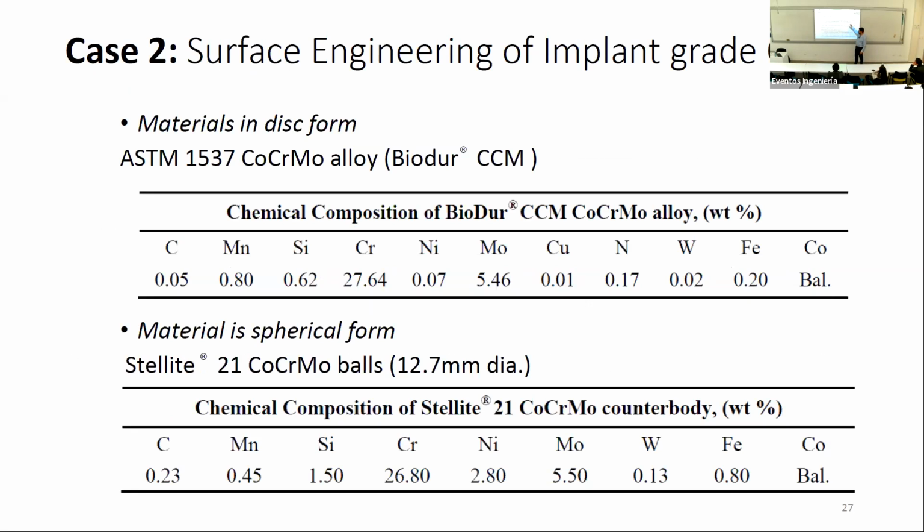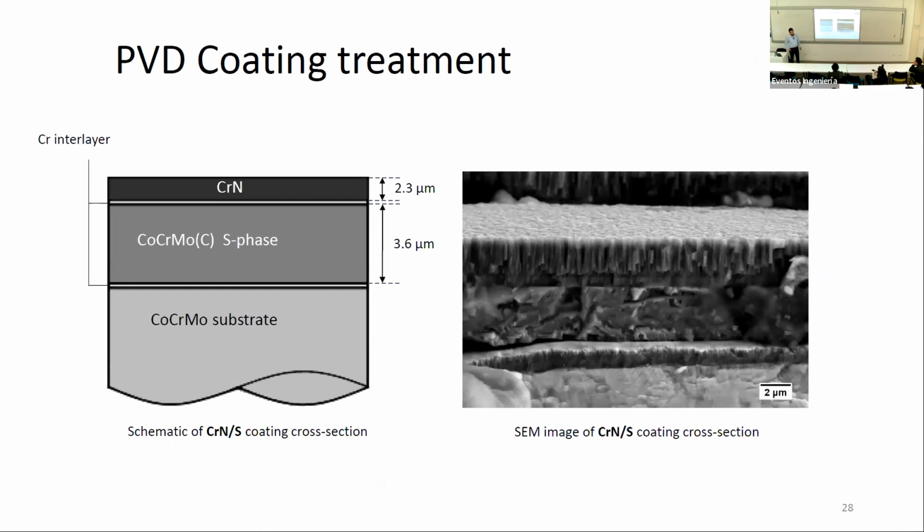So we used a biomedical ASTM F1537 alloy for the disc, and we used Stellite 21 as the counterface ball, as the counterface material. In this case, we only looked at this coating, cobalt chrome molybdenum S phase deposited via PVD, followed by chrome nitride.